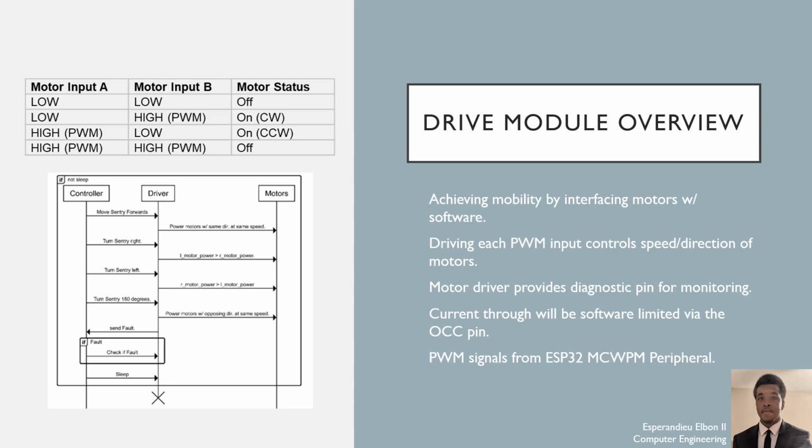With the motor driver's current monitoring pin, we will dedicate a pin on the MCU to reading its voltage level. That level corresponds linearly to the amount of current that the motor is drawing. If the motor is deemed to draw between 1 to 1.5 amps, the software will stop the motors by disabling the drivers, thus preventing stall from being reached and lowering overall average power consumption. Output from the diagnostic pin immediately stops the drivers until software deems it safe to restart operation.